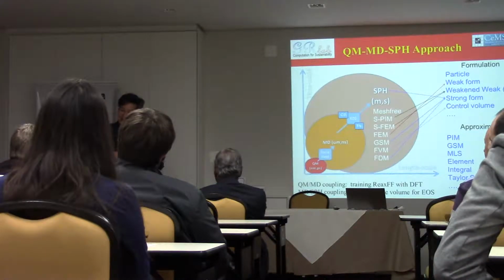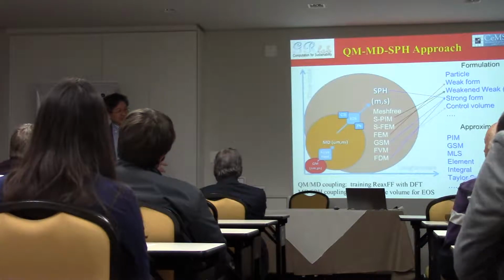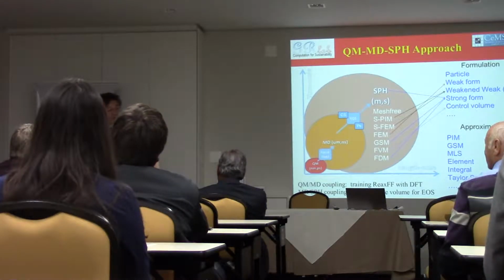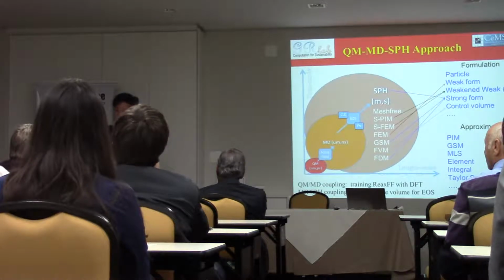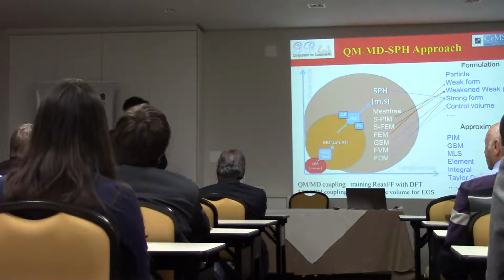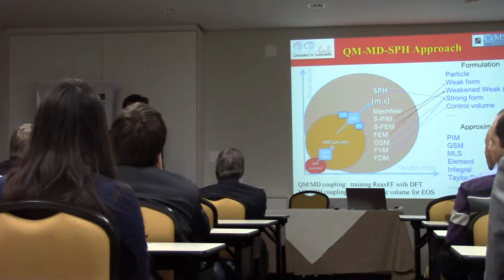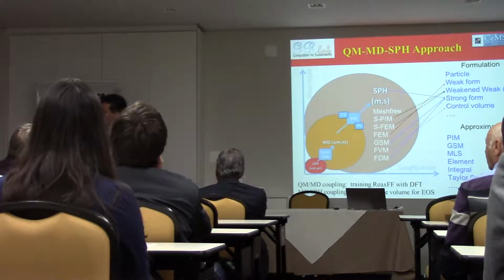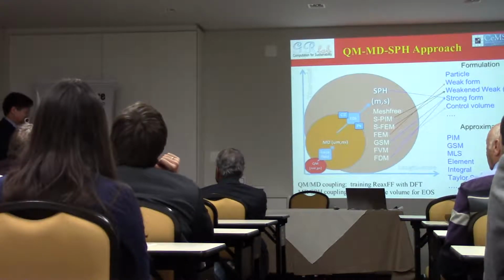Now, when you come to MD, the equations actually become much, much simpler. If you get a proper so-called force field, then you don't need to worry too much about the stability and things like that, because you have the potential there, meaning that the system is stable. So all you need to do is develop a proper time integration technique, and you're marching forward, and you get your solution done.